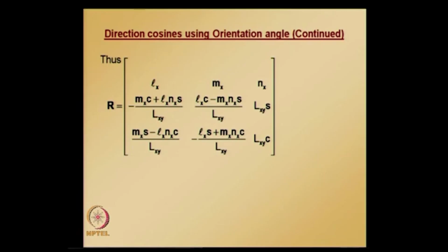This is more general, this is applicable even for the case where local y axis is in the same plane as global x y, and here also Lxy is in the denominator, and as in the special case you have seen earlier, if Lxy is 0, then there is a problem in using this equation.